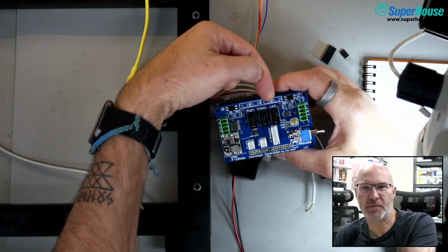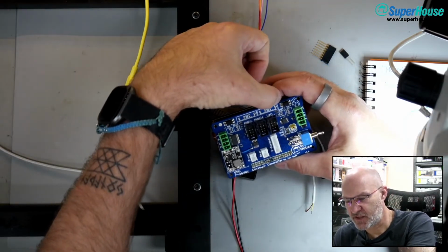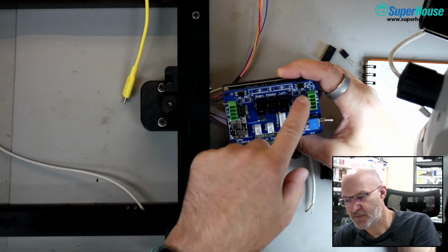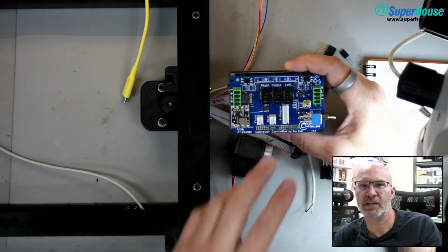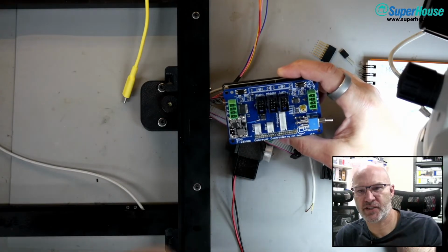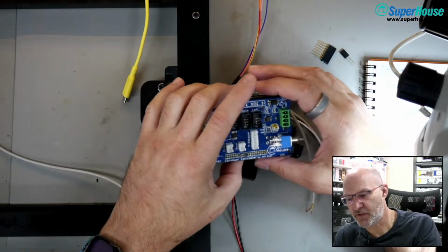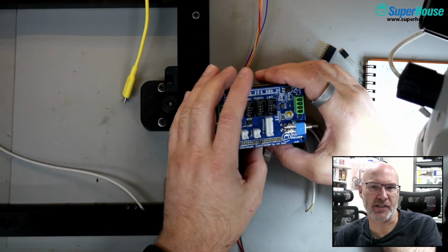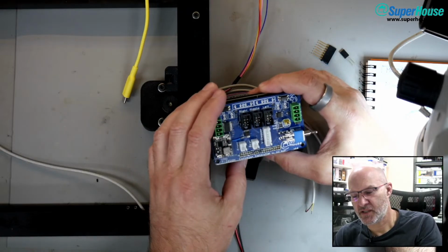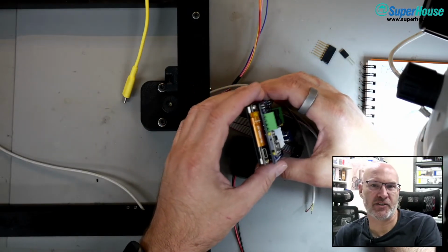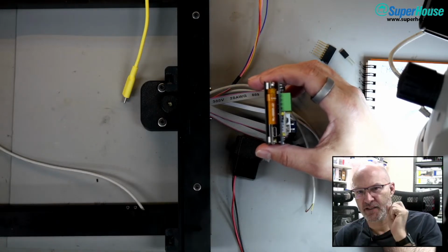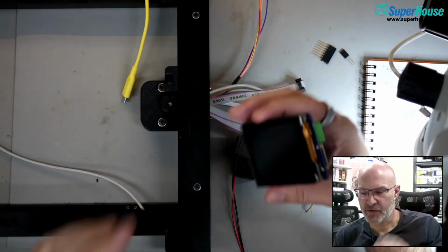which is not actually populated on this PCB at the moment. You can see that it's got positions here for reed relays, and it's got in and out connectors here, which are the ready in, ready out connectors that go to the adjacent machines in the chain. So for example, if this was feeding into a pick and place machine, so it was on the input side of the machine, what it would be doing is looking for the ready in connection on the machine, so that when the machine asserts that signal, it says, yes, I'm ready for a new board.